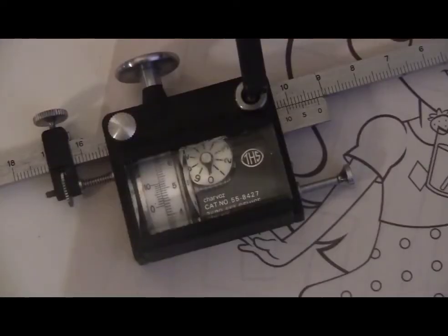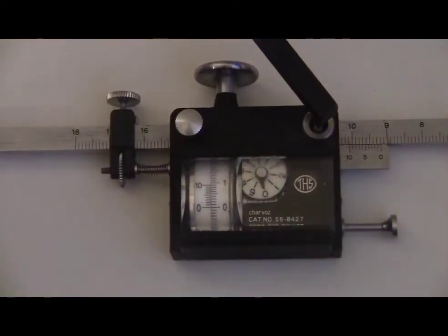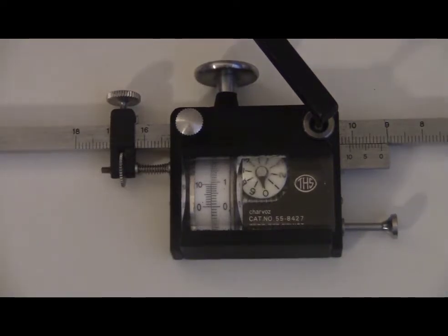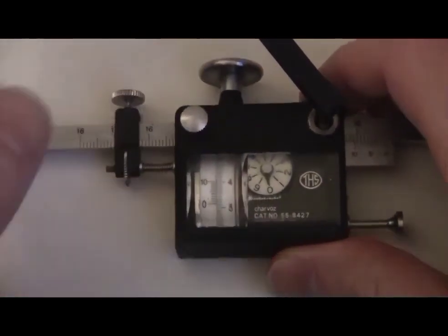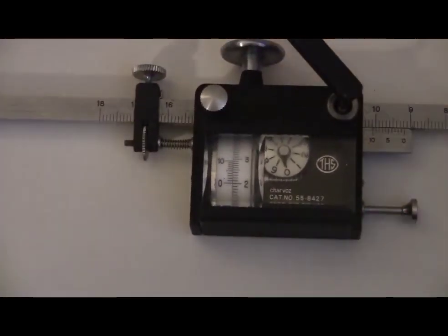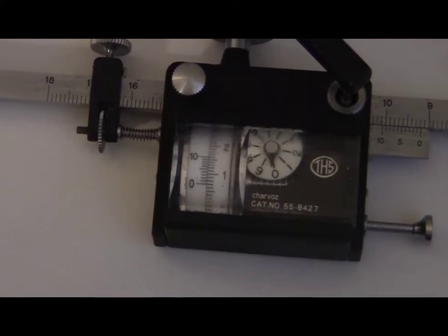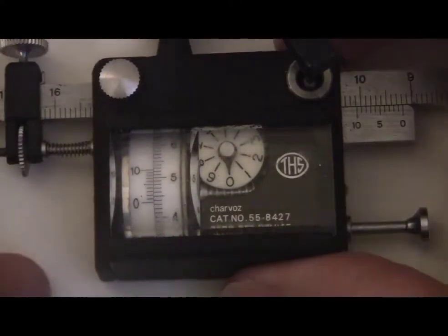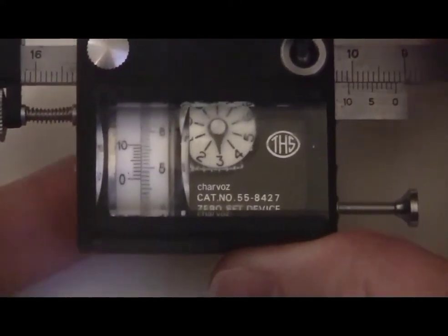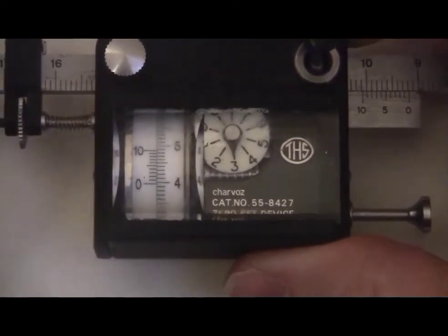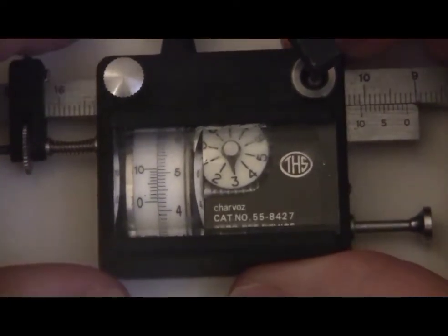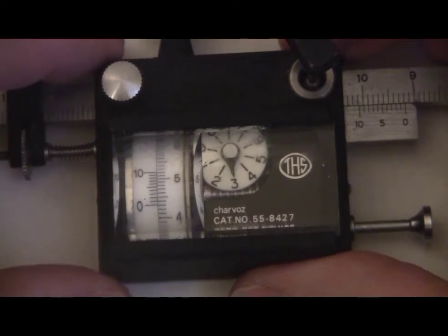This planimeter reads in square inches, and you read the answer by lining up the 0 on the left with the dial on the right. So this would be 0 square inches, and this would be 2 square inches. This here would be 0.7. The round flat dial on the right is for tenths of inches, so this reading would be 34.3 square inches. The big 3 over there means 30, and then you've got 4.3 on the measuring wheel.